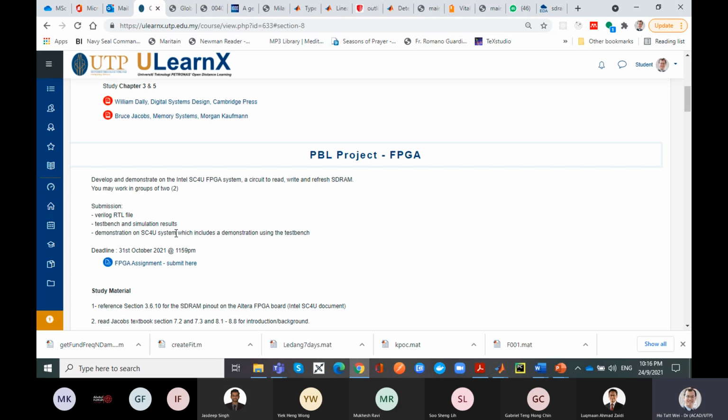What is nice is that Intel has come up with a system where you log into a cloud system, which is nothing else but one of the PCs sitting in the Intel lab. That PC has an FPGA connected to it. You can look at the FPGA and program it directly. And if you need certain pins connected to a logic analyzer, you can do all of that. So there is already a setup where you can test this on FPGA at a distance.